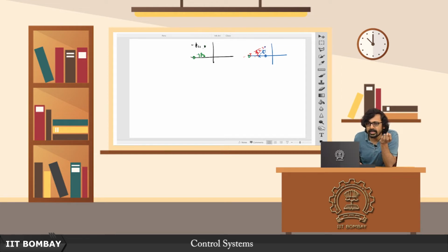The moment you cross this green line and draw this theta z, it will become a parallel line, because these are alternate angles, this is theta z and this is theta z, so alternate angles form parallel lines. Until you cross this, any point to the right of minus z is a potential point to place your lead compensator's 0.